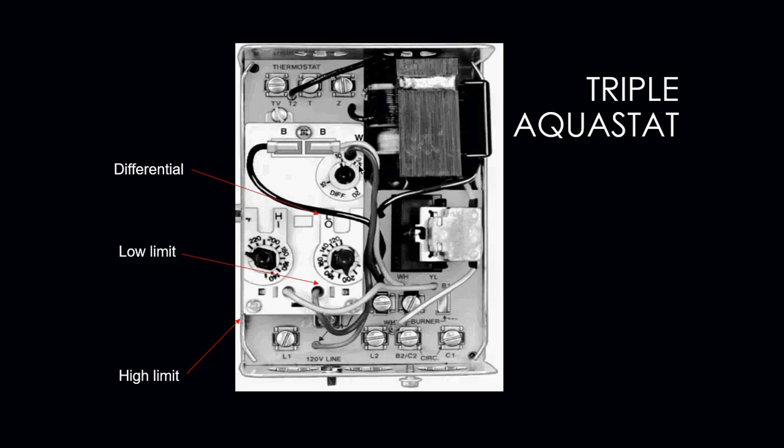And again, like it says, you could do it depending on your specific application and what you're trying to achieve. Can you set it to that? Yeah, you can. But most residential and most mechanics will set them anywhere between 10 and maybe 15 for your differential. Your high limit setting is right here.